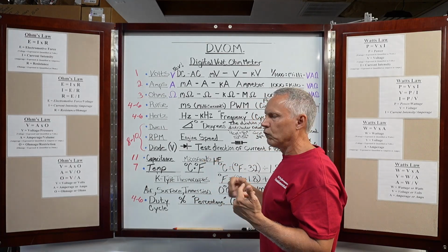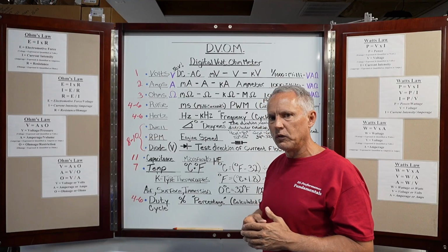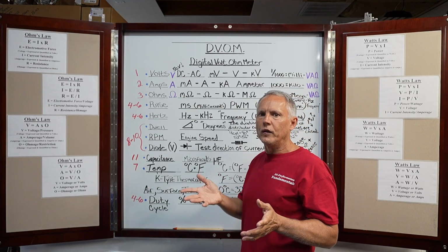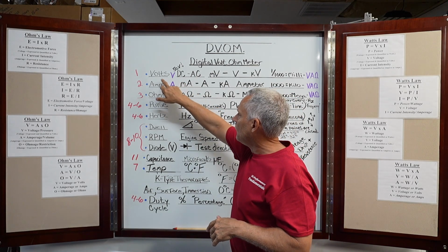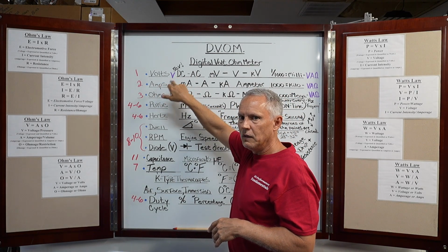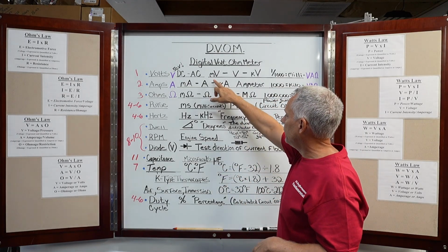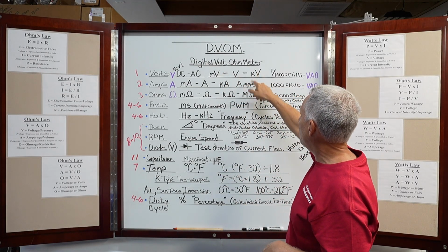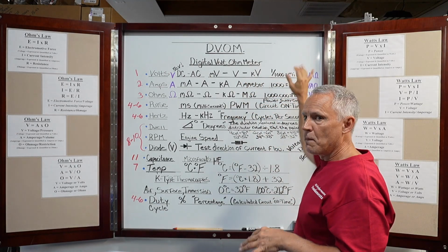But you also learn over the years, what is an AC voltage generator, what circuits have AC voltage, you'll learn these things over time. So basically we're talking about direct current, so voltage, DC voltage, or DCV, direct current voltage, all right? You're going to see on your meter a small m with a V, small k with a V. Those are the ones you're going to use the most. Now, you can go on beyond that, right?